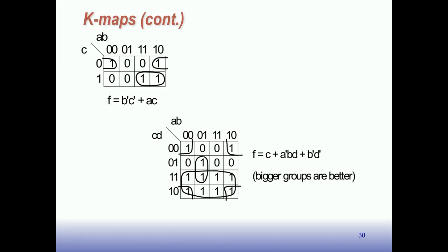Yeah. So you partition the 4 input literals this way to form the row and the column. Like A, B, C, D are the original inputs, and then you put C, D, A, B on. Like how do you know to do A, B and C, D versus A, B, C, D? Oh, it doesn't really matter. I put AB on this axis and CD here. Could you put 3 on one and 1 on the other? Well, if you did that, you'd have this long, thin thing. Then you would miss out on seeing some of the adjacencies. So you might be able to do it that way, but I don't think it would work well.